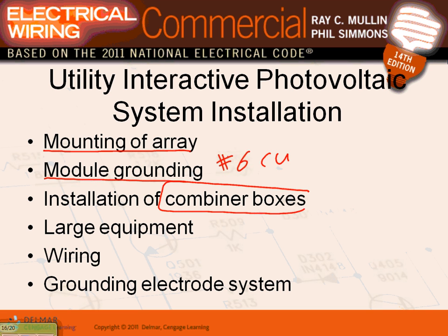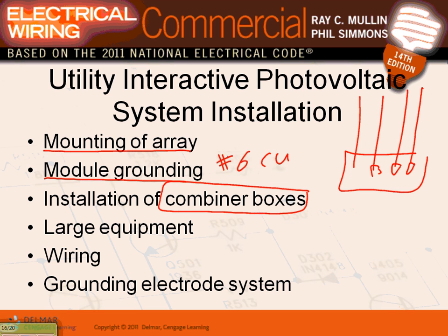Combiner box: here's my combiner box, and here's all my strings coming in, and we can fuse them and diode them, and from this side they're coming out and going to the inverter. Large equipment, wiring systems that we're going to be using.